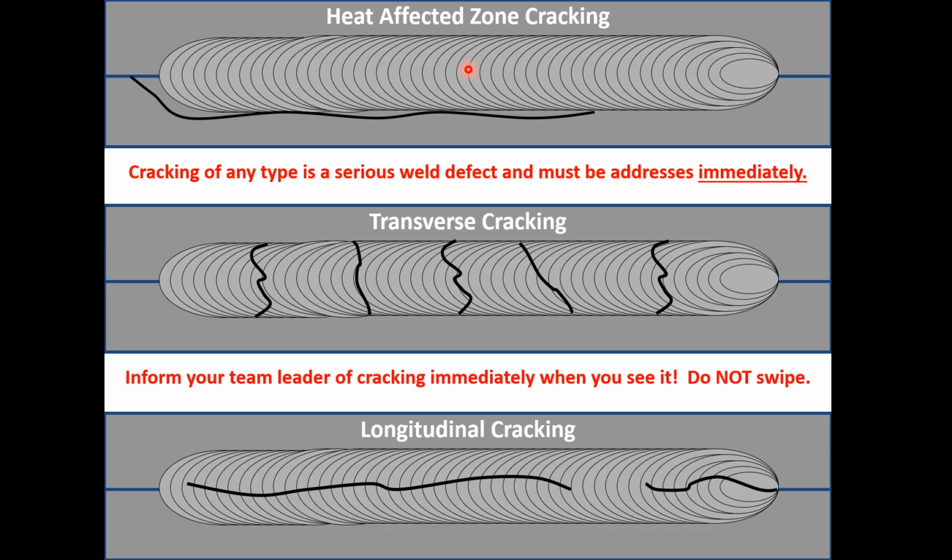So sometimes you can weld certain types of materials that give us all kinds of problems. Boron steels come to mind. They were also known as hot stamped. They have some metallurgical problems where the weld itself, that spike of heat, has caused hardness of materials. This first one is often what you see in the field, but I've seen it occasionally when we're welding specialty metals where our welding process has either not been hot enough or we didn't use quite the right filler metal we should have, and we've caused some embrittlement right in the heat affected zone.